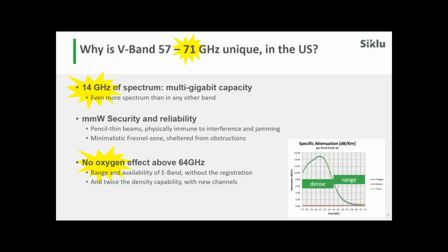So, our 614TX is first of all standard PoE input. If you have a device that can deliver 60 or 90 watts of power, if you look at the combined 52 watts and 26 watts that the radio itself needs, that's 90 watts. If somebody wants to connect the 614TX to a standard PoE PSE device, the 614TX is a PoE PD, powered device, and will run the correct protocol to make the switch provide the amount of power that the 614TX needs. So that's that standard option.